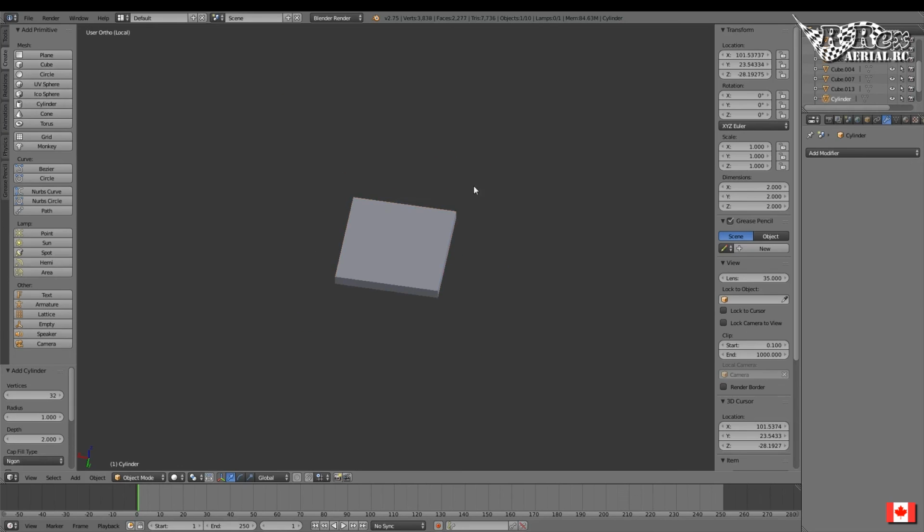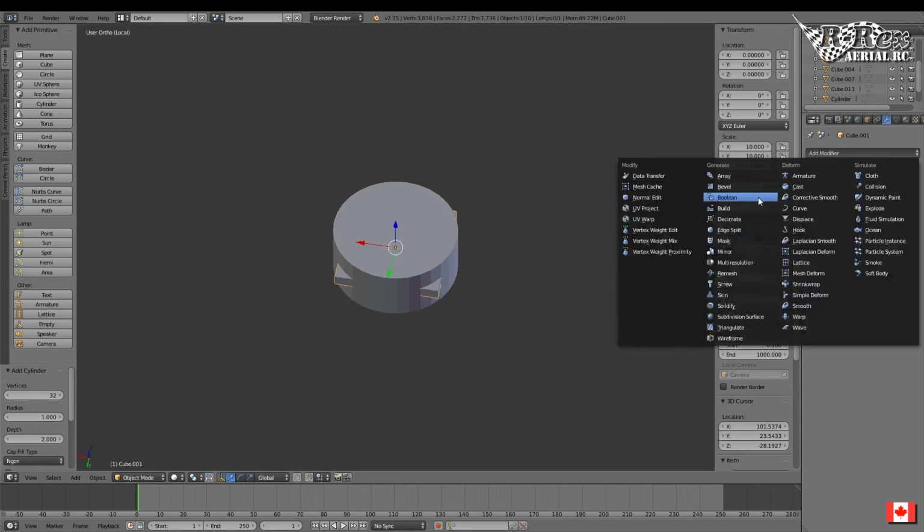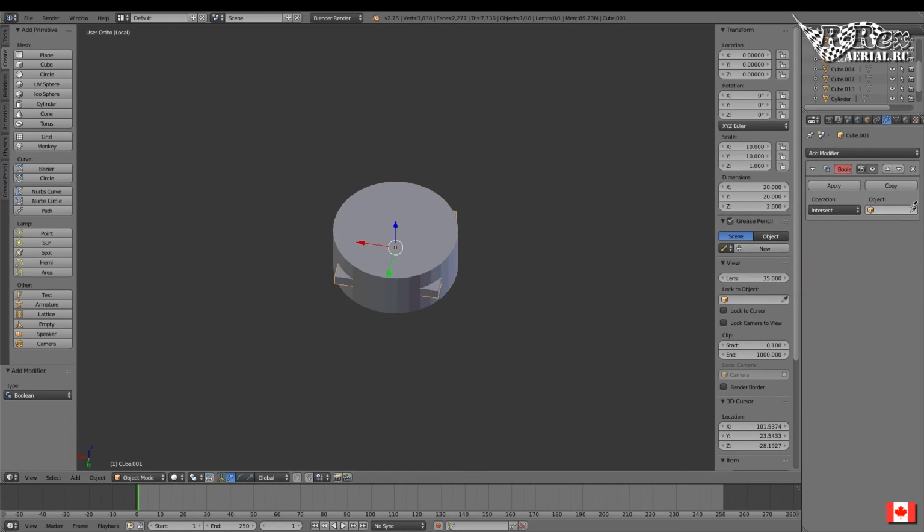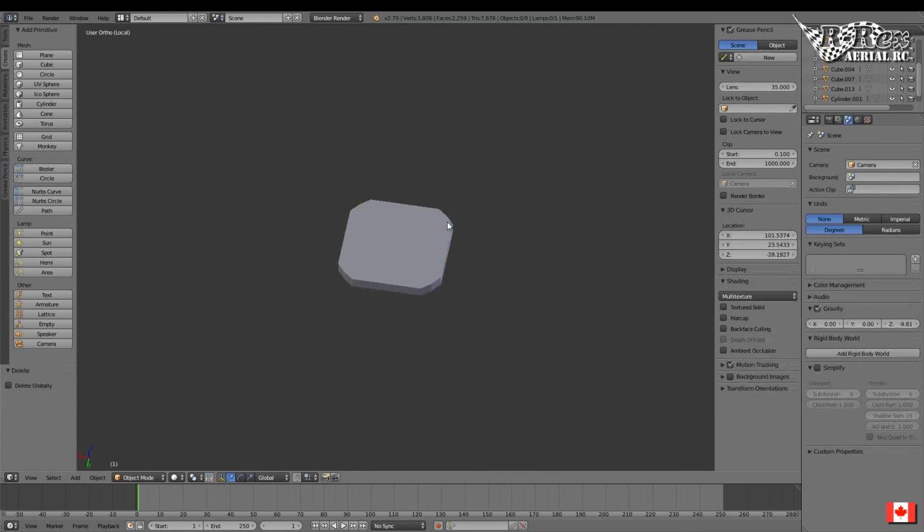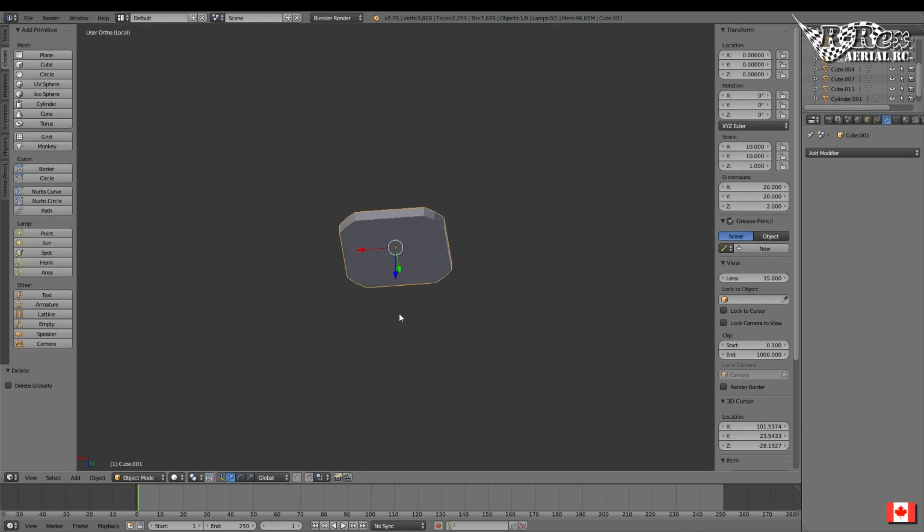I'm going to create a cylinder. The cylinder is going to be, let's go 20 by 20. We're going to zero it out and give it a 10. Now we want rounded corners, so let's do 24 by 24. If I select an object and I go Boolean intersect, it'll actually only allow the object that existed inside of the object that I selected to exist. Press apply. I can delete the object that I used, and now I have a cube, or a square with rounded corners.